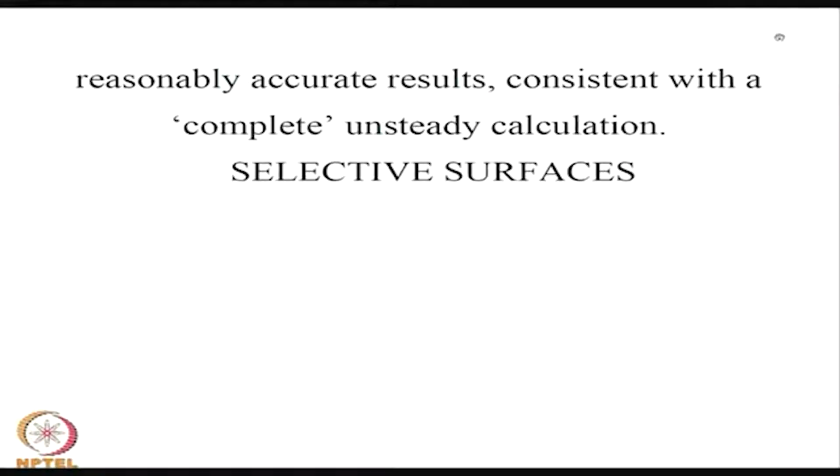And particularly if m C_p is large, the response will be slower. So, you are likely to get a fairly accurate result, and this is most important from the point of view of whether the collector will reach the required temperature before the solar radiation reaches the critical level of radiation. It can be more, but it cannot be less, because the critical radiation level corresponds to the temperature at which the energy delivery is desired by you. So, the collector has to reach the temperature before that time.